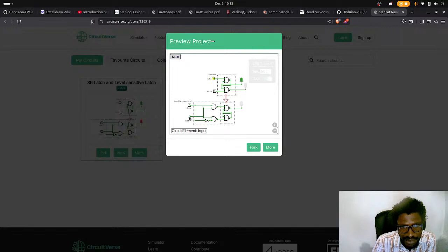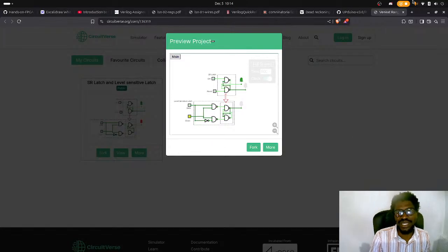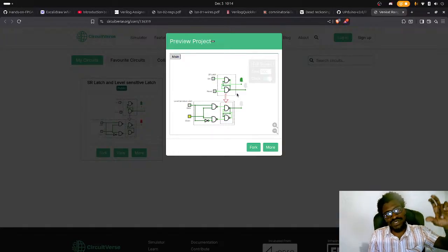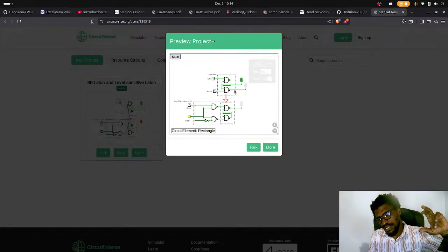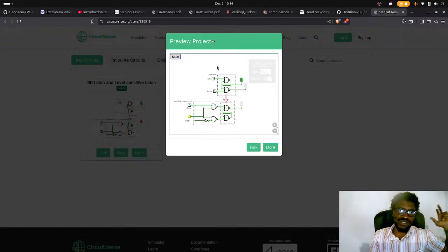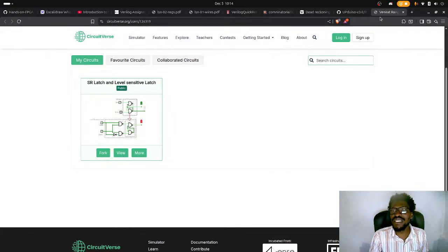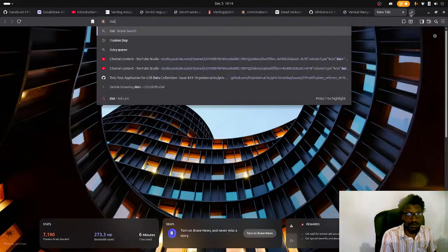Okay, and then here we have a data. Let's set this data bit, and then we want to toggle the clock. We get a green LED. We untoggle the clock. So it depends on the data changing again. Basically, what we're trying to show here is that these two digital logic blocks are the ones that form the basis of clocks. This is how clocks are made. Clocks are basically made using D flip-flops, data flip-flop, D flip-flop.